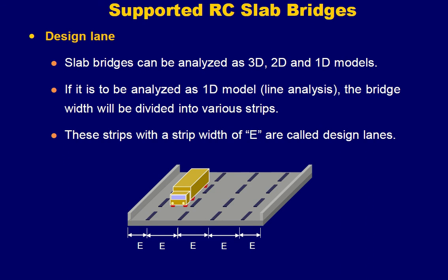So now coming to the design lane, slab bridges can be analyzed as 3D, 2D, and 1D models. Okay, so of course 3D model analysis will be much more accurate as compared to 1D model, but at the same time the analysis of 3D will be much more difficult than 1D models.